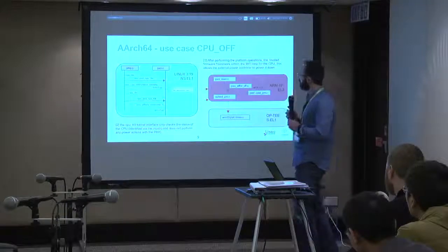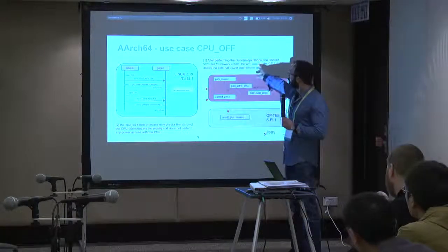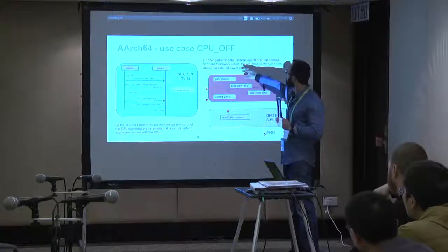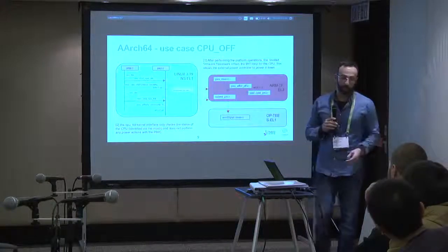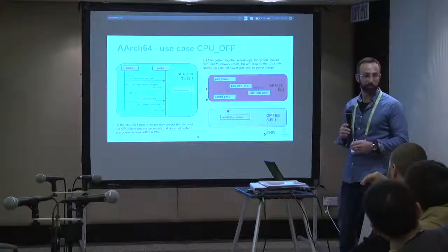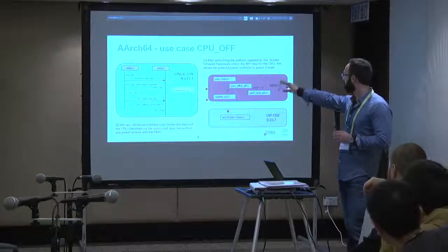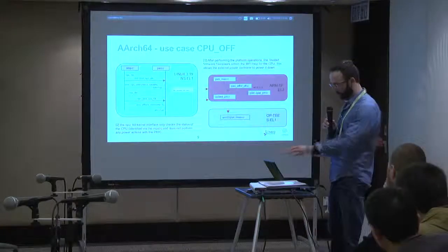So basically, the way it's supposed to be working, you do all the platform operations, the Trusted Firmware framework, enter the WFI loop. At some point, the PMIC will switch off the CPU, and then another core will go into the kernel. Another core in the kernel from the SMP code will check that the CPU was switched off.